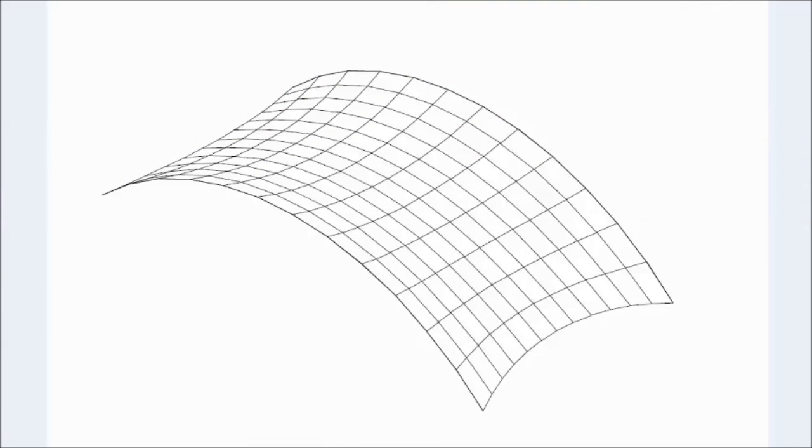The essential starting point for an FEA stress analysis is a good understanding of what results to expect, either from prior experience with similar structures or from a thorough estimate of the stresses. We can then use FEA to get more exact figures for the deflections and stresses, while using our general idea of the expected result as a reality check on those figures. In this video, we're going to learn several simple ways to make careful estimates that will enhance our understanding and use of FEA. Let's spend a moment talking about how a tensile structure reacts to loads in general.